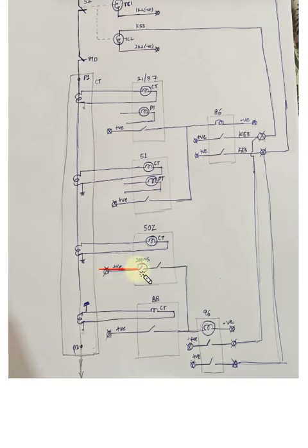If the 200 milliseconds has finished, then it checks if the fault current still persists, and then it extends a command to the bus bar. It uses the trip circuit of the bus bar protection, and it trips the entire bus. Okay, so whatever feeders or transformers are on the bus of that section, all will trip, and the bus will become dead. Okay, so we'll see how the bus bar relay operates.